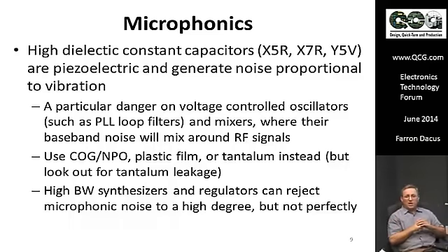So allowing that dynamic range means that you typically have to work down to the noise floor, and I mean the thermal noise floor. You don't want a lot of other things degrading that noise floor, and in a high vibration environment, say on an aircraft, that can easily happen: the jet turbine vibration will shake these capacitors and generate a lot of noise at the turbine spin rate. And so you have to be real careful in the usage of those kinds of capacitors.